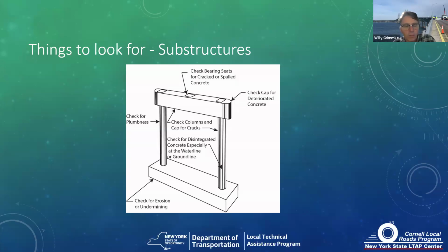Particularly at the mud line, water line, ground line. Is everything plumb? What do those pier caps look like? Do you have spalling concrete, exposed rebar?